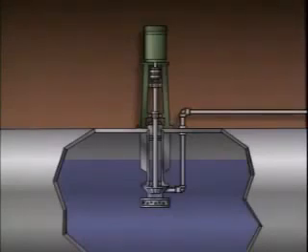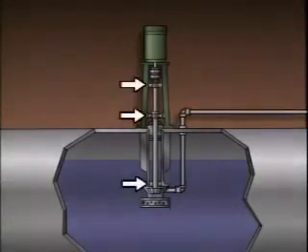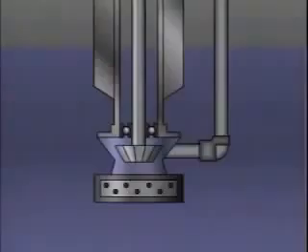so that the pump will operate properly. So several bearings are used to keep the shaft properly aligned. Now on this pump, there is no suction piping. Instead, the suction of the pump is submerged in the liquid being pumped. The suction is covered by a strainer, which prevents trash or debris from clogging the pump and causing excessive wear.